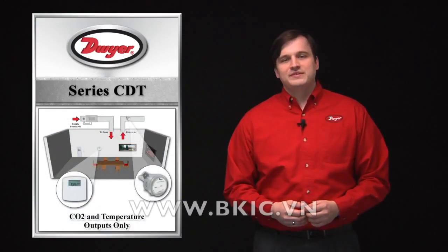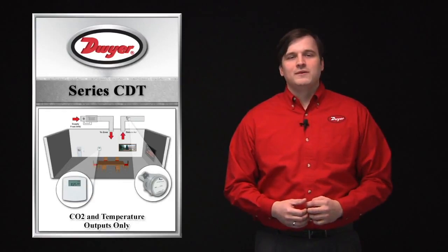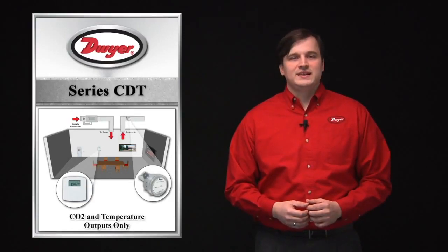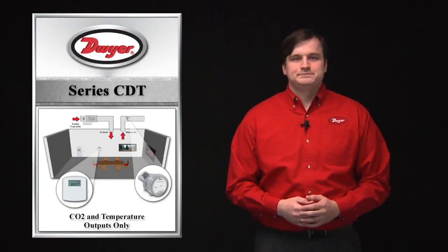The CO2 output signal can be field selected between voltage and current options, while various thermistor and RTD temperature outputs are offered at the time of order to match the input needs of the building management system.